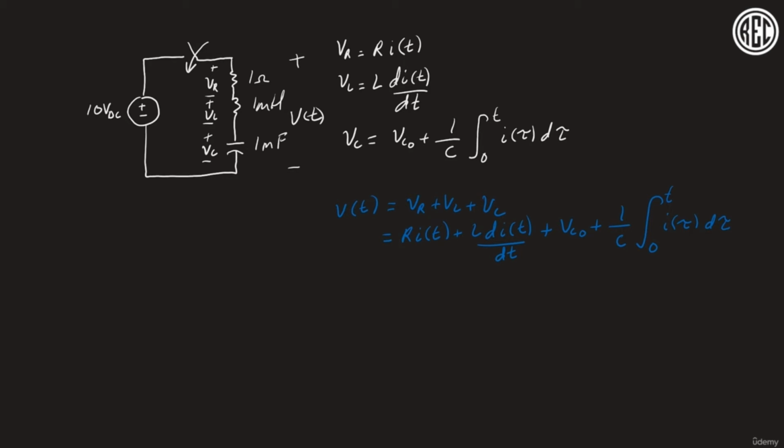So we can say then that this equation is going to become 0 because again, the derivative of v of t is just 0 because v of t is a constant, and then times R times the derivative of i. So again, we're taking the derivative of all the terms in this equation over here. And I'm actually going to divide every term by the inductance L. So I'm going to say R over L times di dt. That would be this term over here again, taking the derivative of that term and then also dividing it by L.